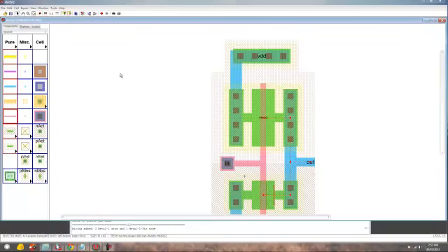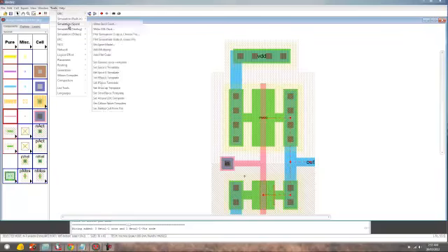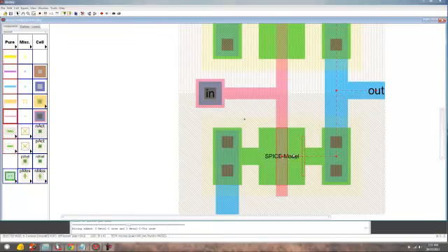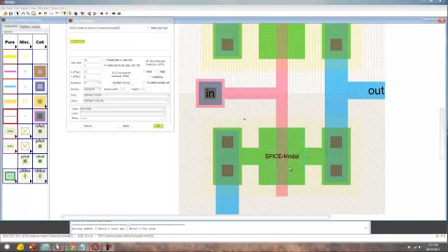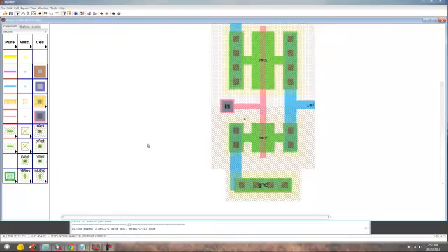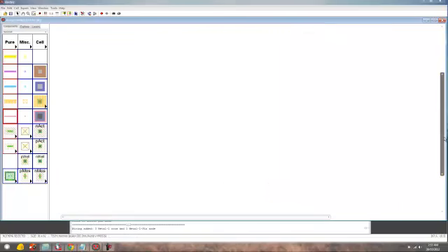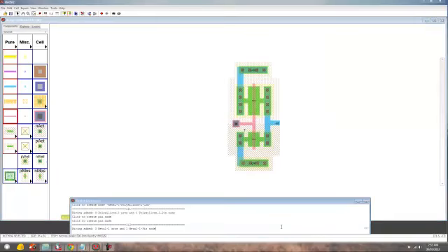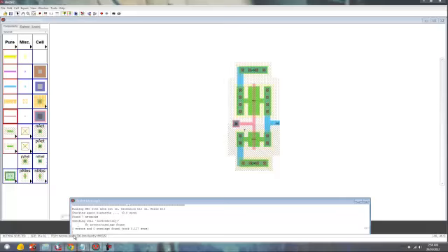And do the same for the bottom one. Click on that, make sure the connection is correct, the red dotted line. So again, Tools, Simulation Spice, Set Spice Model. And the same thing, Control I, change it to NMOS. Okay, this completes our layout for the CMOS inverter. So check F5, no error.